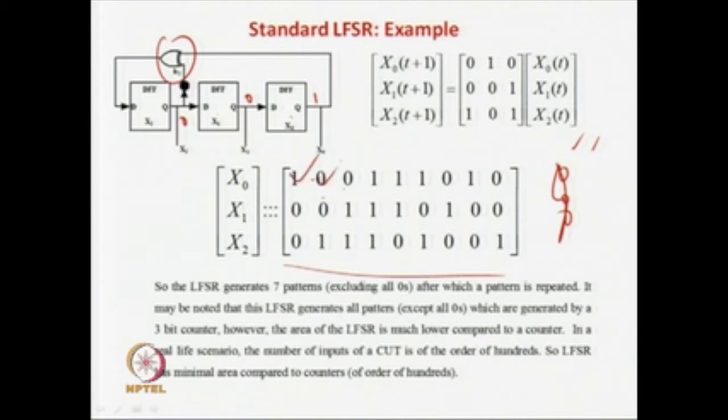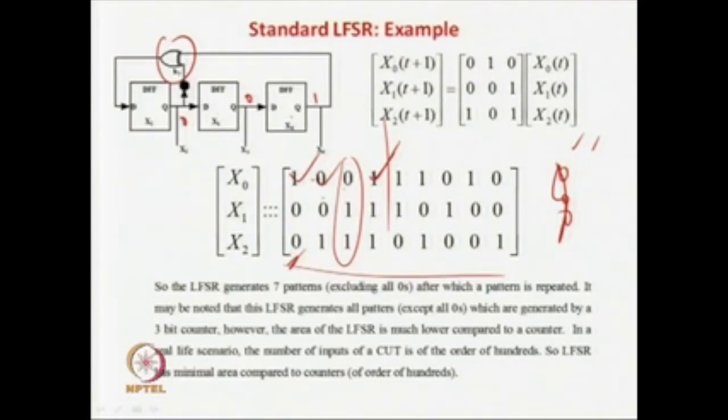Our requirement is this one and this one. So, only if we start with this seed, and we get one in sequence pasted, all the others are very good for us. But if we start with this seed, then it is a problem, because this is an important requirement, an important pattern, but then again you have to get all these junk patterns there before we go back to this one. So, seed selection and characteristic polynomial selection is very important.